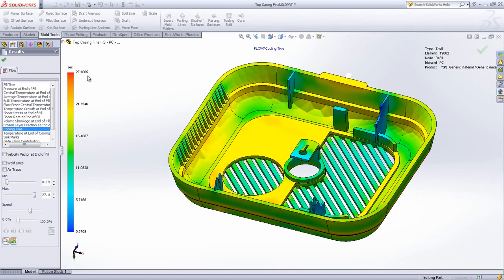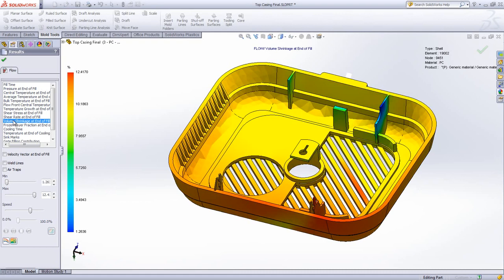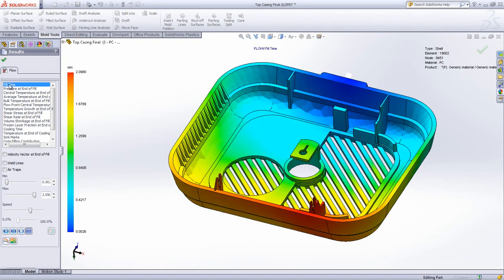It's because the wall thickness usually drives the cooling time, and the cooling time is often about 70% on average of the overall injection molding cycle time. This means that by improving the geometry of your model, you can reduce the cycle time and also lower the price per part.